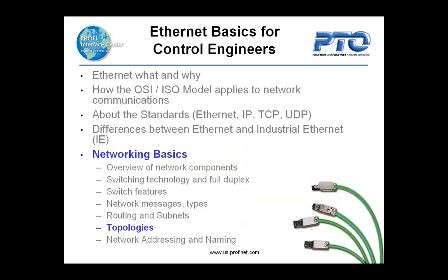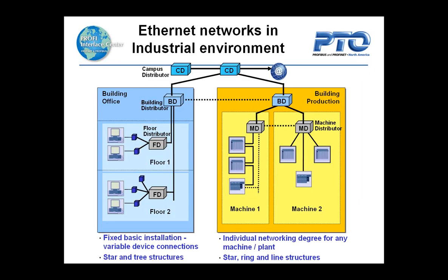Okay, let's talk about network topologies a little bit. Because we know that Ethernet networks in the industrial environment are a little bit different again. A lot of times in an office environment, in a building, you're going to be talking about having a fixed installation. And a lot of times you're talking about a star structure or a tree structure where everything's coming back to a single point, or maybe a single IT room where all the switches are in that room.